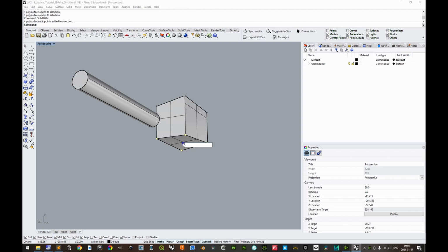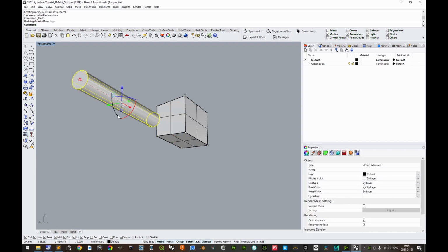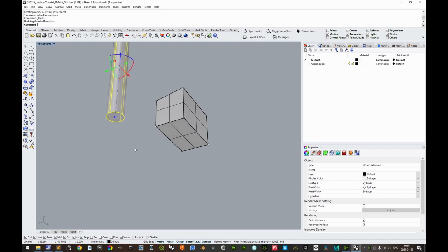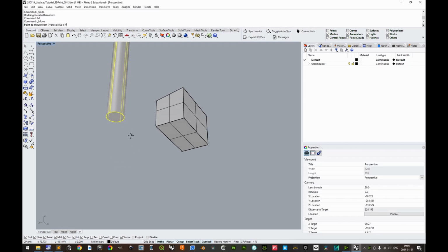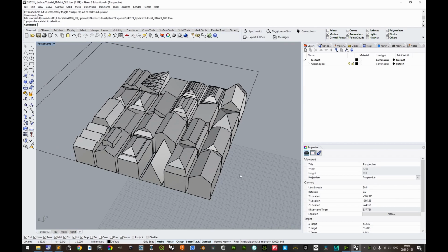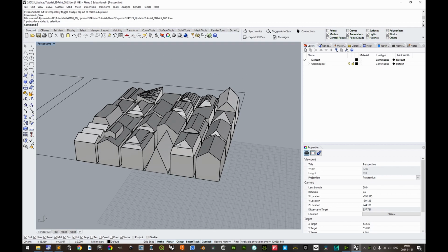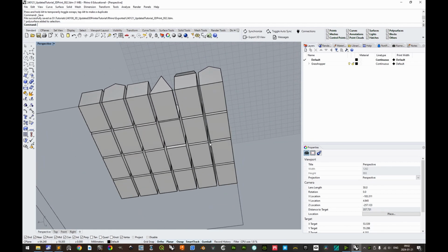If it is not, then it will severely affect the workbed adhesion, since the relative adhesion area for the object is reduced significantly. If the geometry allows for it, make sure to rotate the object in any way which utilizes any completely flat surface as its bottom surface. All objects must have their flat bottom surfaces completely horizontal with regards to each other.